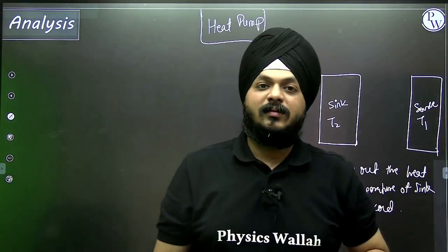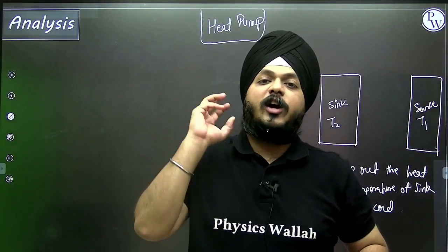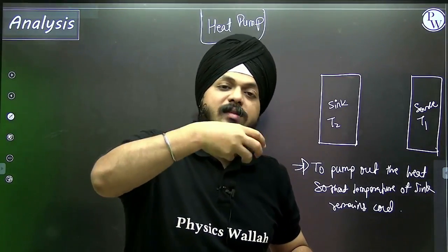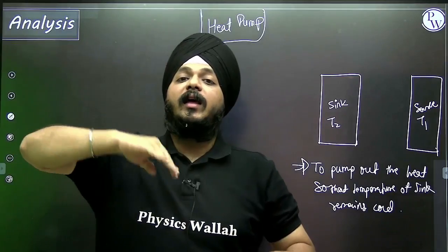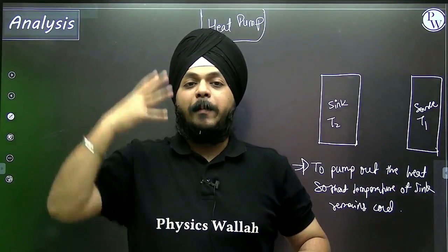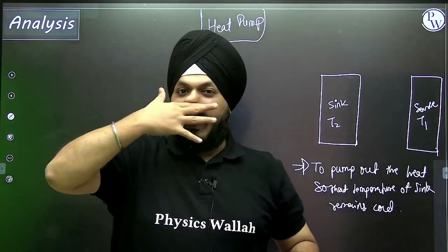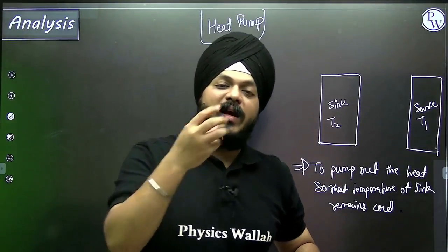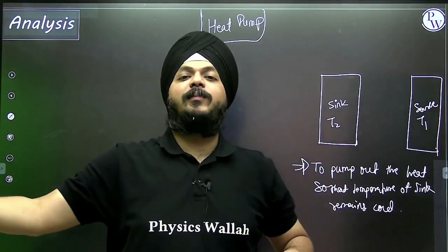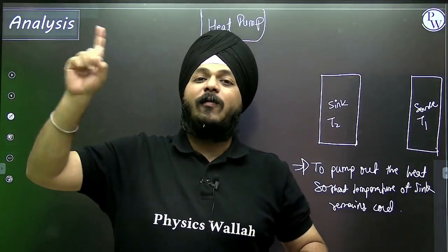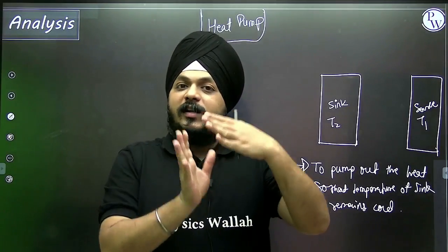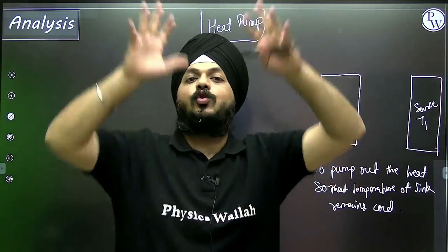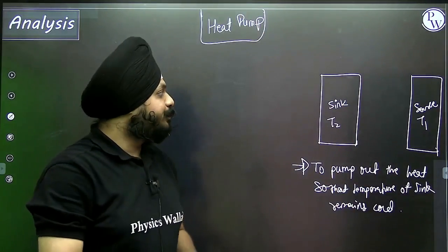You will hear a sound. That sound itself states that the machine inside is continuously pumping out the heat into the surroundings. The back part of the refrigerator is warm. Why? Because the machine inside is continuously trying to pump out the heat from the refrigerator to the outside environment, so that the temperature of the refrigerator is maintained and things inside have a cooled environment.